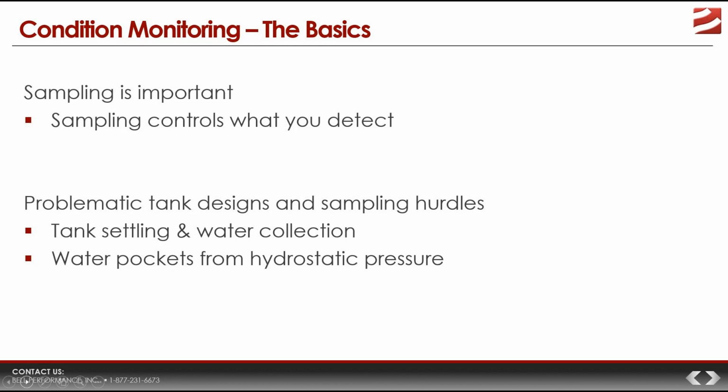Now, even an issue as simple and yet as out of our control as tank design and tank settling can have major impacts on our ability to detect and remove water, which essentially means they are integrally tied to microbial growth issues. See, it's not uncommon to take a fuel tank and check for water and have zero detected free water at the fill end, and yet down at the turbine end you've got like 50 gallons of water sitting there that you didn't really know about.